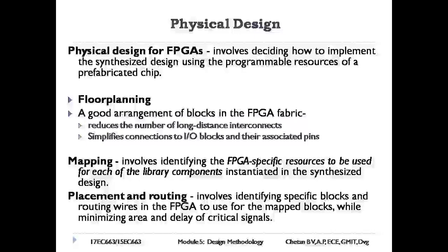Placement and routing. Placement and routing involves identifying specific blocks and routing wires in the FPGA to use for the mapped blocks while minimizing area and delay for critical signals. This is performed by automatic tools, that is, EDA tools provided by the FPGA vendor.